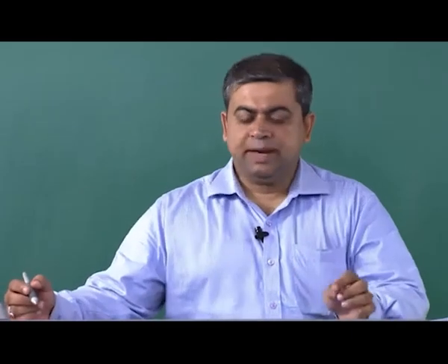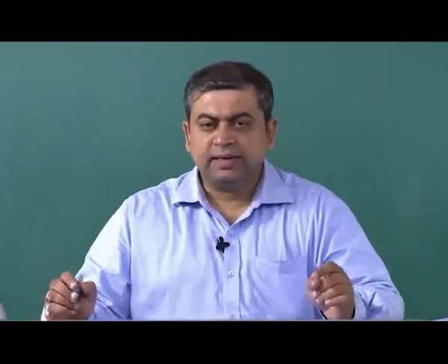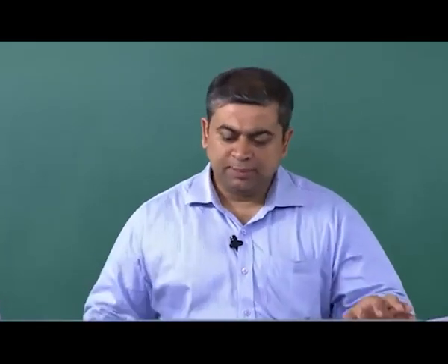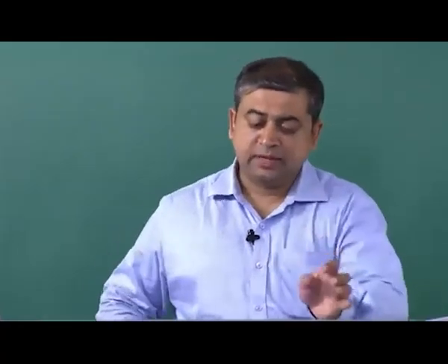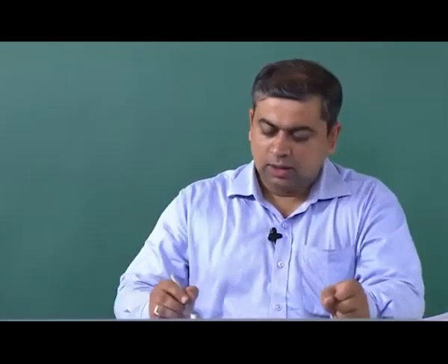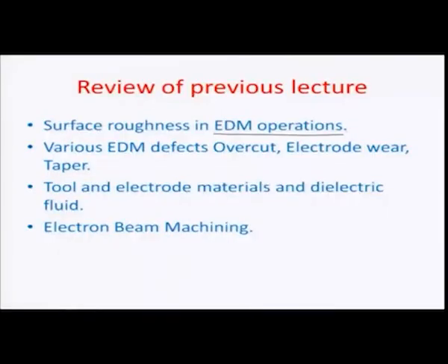Hello and welcome back to this Microsystems Fabrication by Advanced Manufacturing Processes lecture 26. Quick recap of what we did in the last lecture. We talked about surface roughness of EDM operations, electro discharge machining operations. We also talked about the various EDM defects like overcut, electrode wear and taper due to the unequal exposure of the workpiece to the sparks coming from the tool electrode.